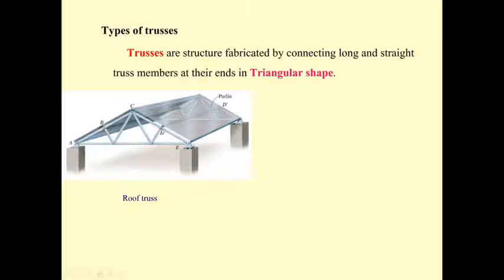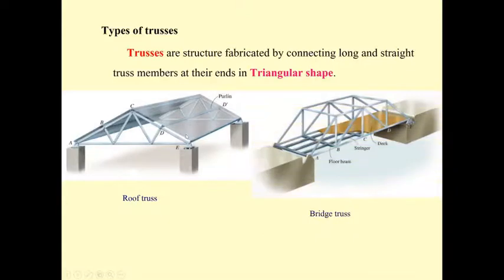And then the joints at the purlin will resist the reaction, and then the reaction at point D will transfer to the truss joint, and point B also transfers to the truss joint. So each purlin will transfer the force into the joints.